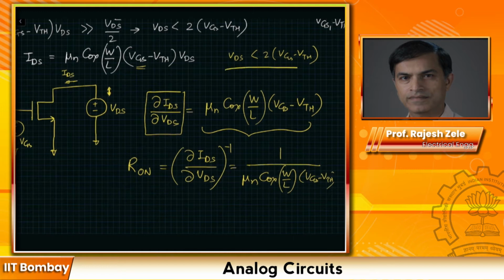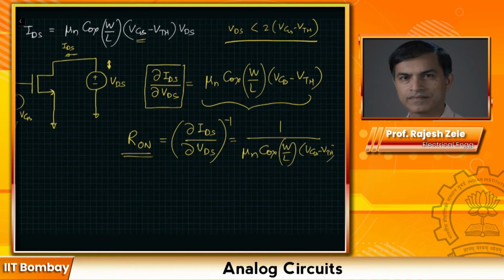The original assumption that we had is that VDS is much smaller than VGS minus VTH. So we say that this is a linear region of operation. Since it looks like a resistor, we say we have a resistance between drain and source. The value of the resistance can be changed by controlling VGS. The transistor is operating in the linear region, also called the triode region.